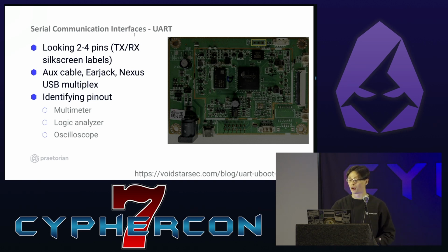In this photo from a VoidStarSec blog post, it seems kind of dim here, but there's that 3-pin interface circled in a yellow box on top. That would be a pretty good target for a UART interface here.